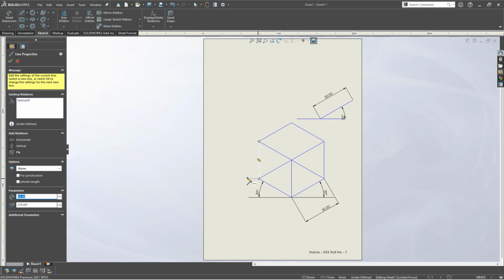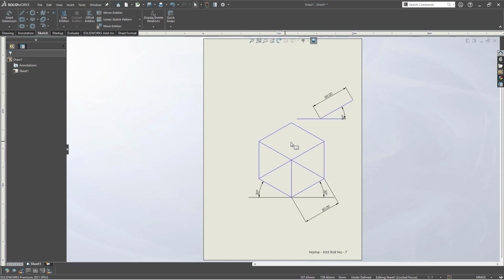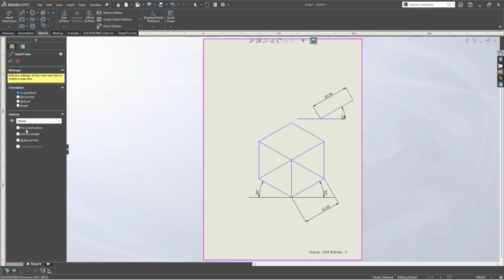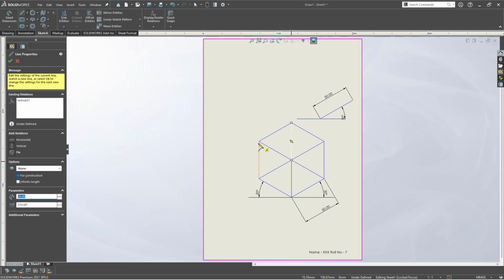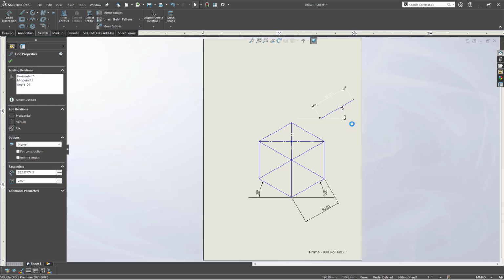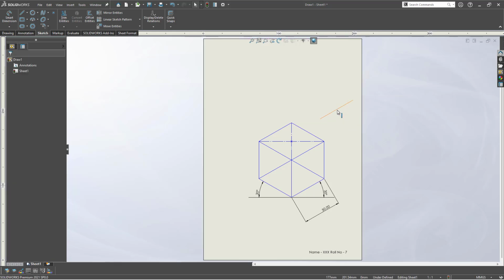And then here one should be there at the center, we should have it. So let me do that again. Just for my reference, I'll activate the line. You can activate for construction. So this is just a construction line for me from here to here, just to extract the center point. Okay, fine. This I would like to delete. You can just select like this and delete. Same thing here. Now we have the exact cube ready with us, right?